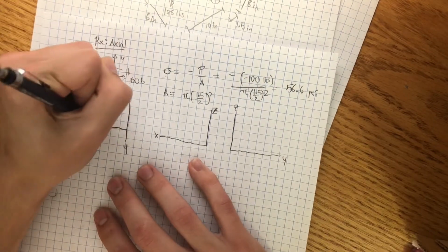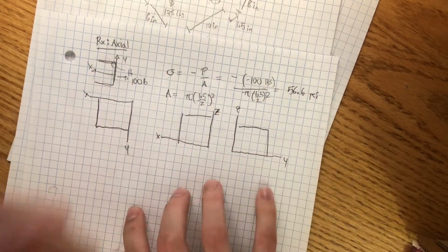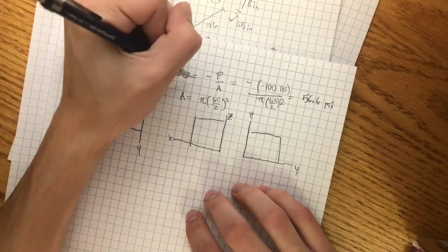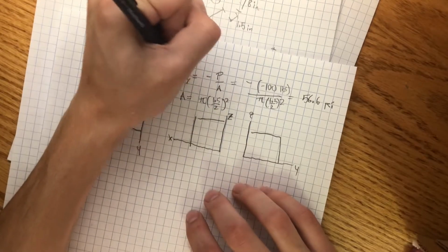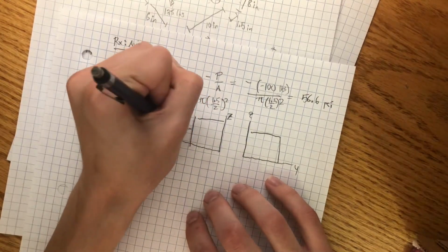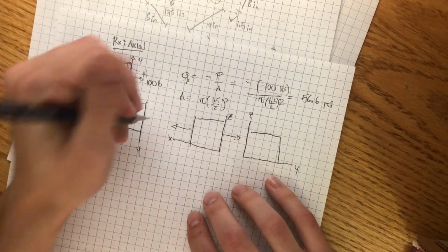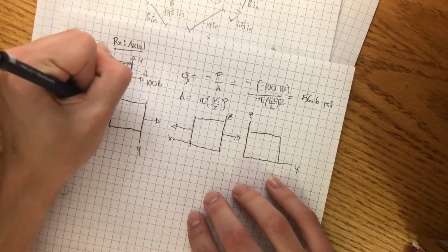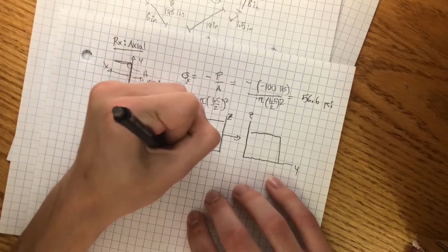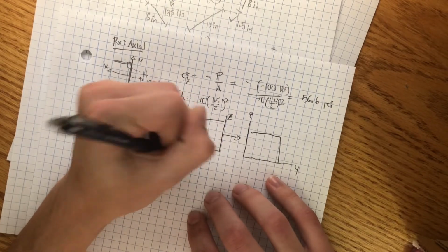So these are our blocks here. And so because we know that this is a stress going in the X direction here, and it's positive, that means we're going to do outwards arrows on these along the X axis. So on both of these blocks, we'll have these outward arrows that show tension, and the value will be 56.6 psi, which is our value for stress, of course.